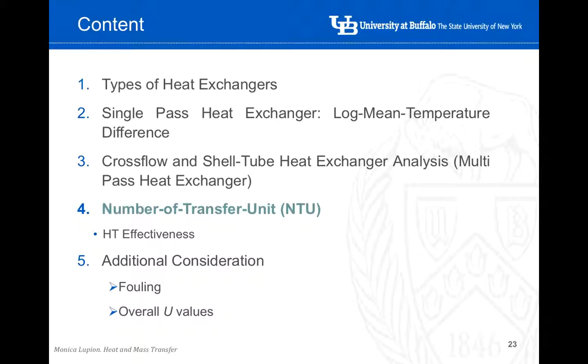You have different examples in your textbook. Basically, what we had to do is to calculate two parameters, Y and Z, depending on the capacity of the system and the temperatures at the inlet and outlet. And then using these charts, we will be able to determine the value of F and therefore be able to use the general equation.